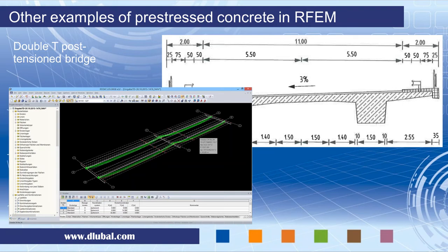The slab had zero stiffness in the longitudinal direction, because in that direction we had these beams, but it has some stiffness in the transverse direction to make sure that those beams share the load applied only on one of them. So that was the model.